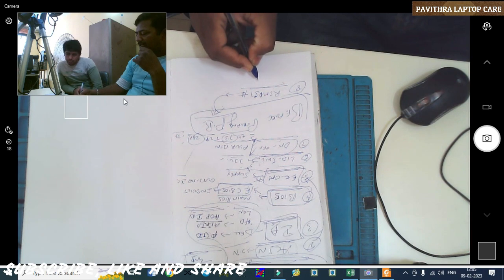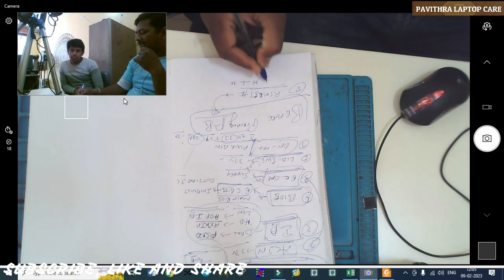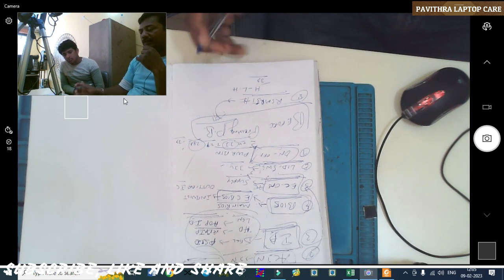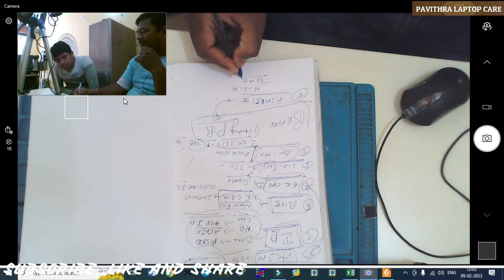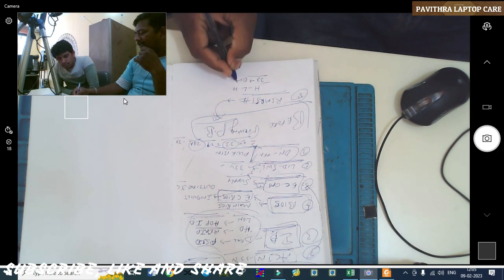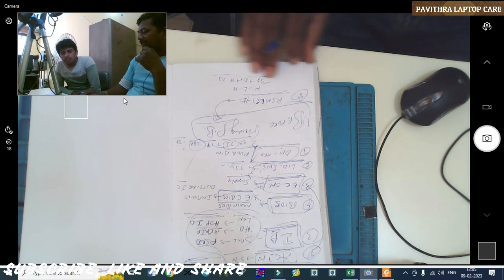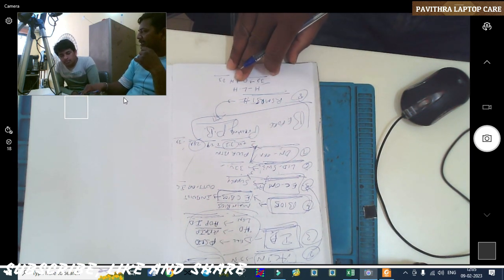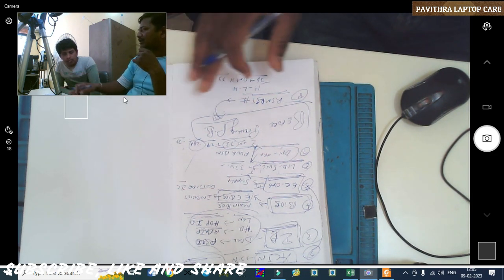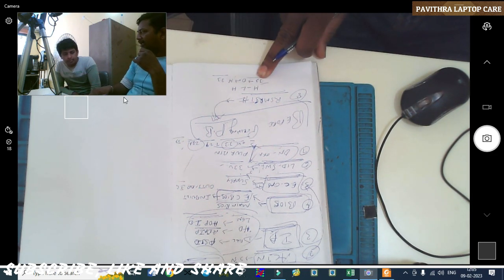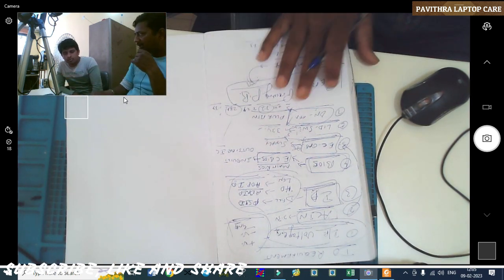This one is high-low-high logic, meaning here already 3.3 volts will be there. When you press the power button, it will be 0, and when you release, it will again be high, 3.3 volts. So it indicates a signal that it's ready, so please move on, please proceed. That is the indication it gives to some other section, maybe the PCH or some other controller.